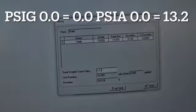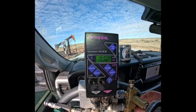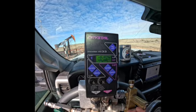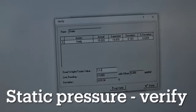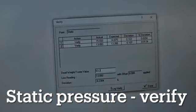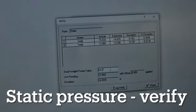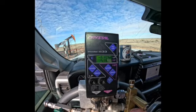So as we start the meter verification, you will see that with no pressure on the meter, 0 is 13.2. I will use the crystal to verify that there is no pressure on the sensor. The first test point will be 13.2. I will type that in as the test value. I like to see the deviation under 0.1%. The company that you work for will give you limits on the maximum allowable deviation.